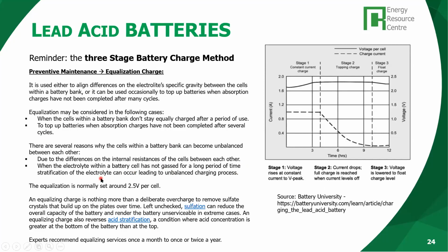Some stratification in the electrolyte can happen, and that can damage little by little, reducing the capacity of our batteries. So in off-grid situations, the equalization can be boosted with a generator set, but in the case of the cemetery, we can use the grid to do this boost charge, the equalization of the batteries, and even program it, as Arnaud has said.